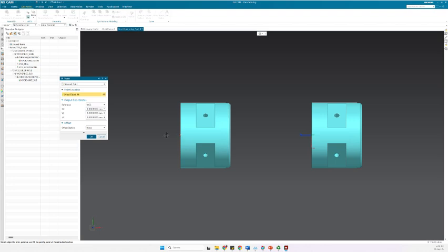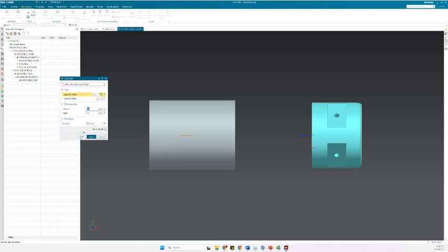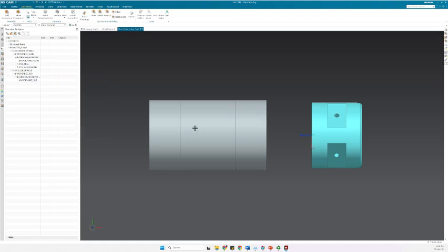And I want to have 20 millimeters of extra material on the left side so that I would be able to clamp it with the spindle chuck. So now let's see what will happen if I put -20. Now it looks like from here the spindle, the raw stock would start. Let's see how that looks here. It looks like it would be correct. I don't know why there are two. Anyway, let's move forward.